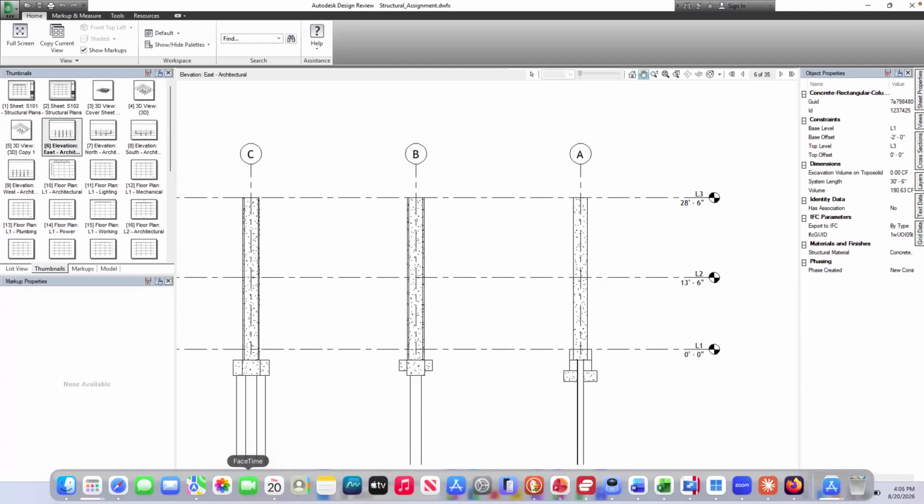Because it's typical, right? So if I do the rebar for one foundation, it's the same rebar for all the foundations, right? So I just draw rebar for one foundation, make a detail out of it, move on. I'm not going to draw rebar for every foundation, in the case of construction drawings, because nobody's looking at the model for rebar. Everybody's looking at the detail for rebar. Questions?